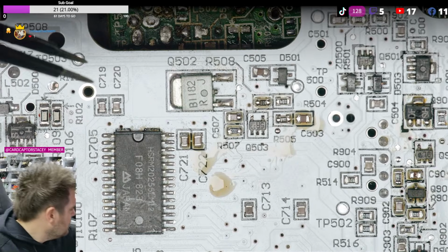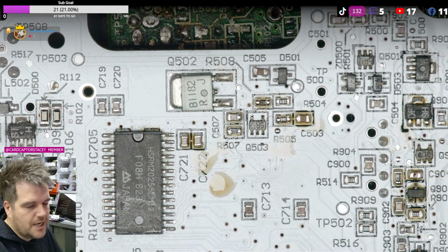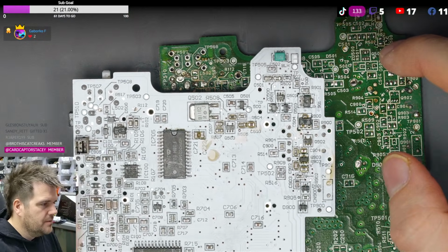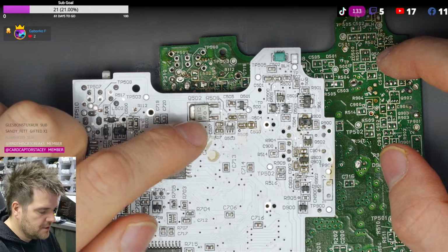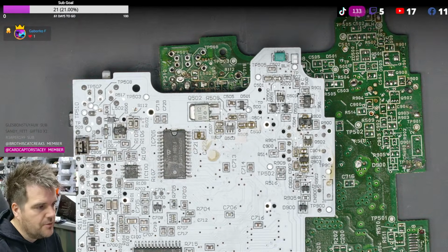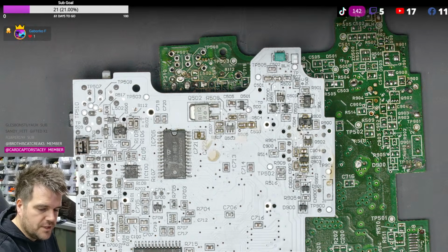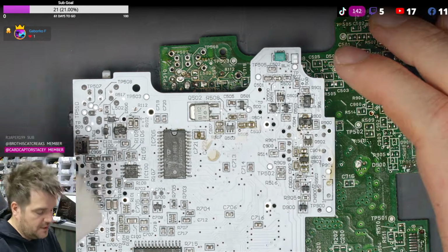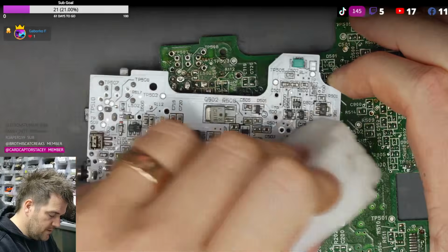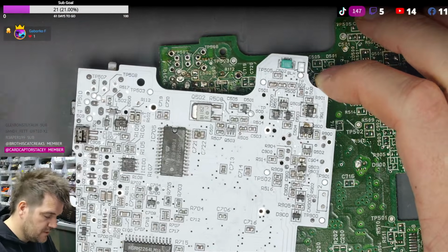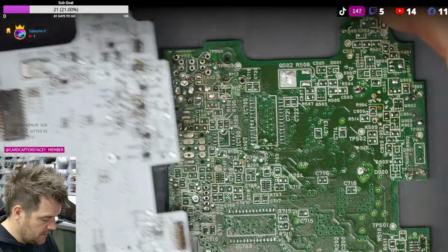And I suppose if for whatever reason we can't actually identify the few transistors that are left, they're on the power regulation circuit, so we could replace this with our own power regulation circuit if we wanted to offer like a pre-populated board with as many components. We could just literally replace this circuit design with our own switching 5-volt circuit. It wouldn't be too complicated.